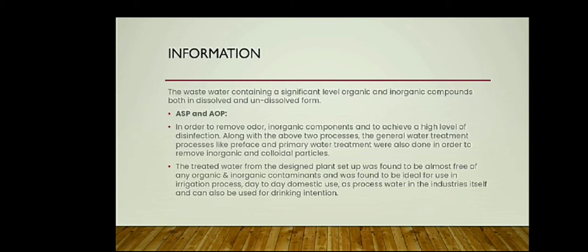This water treatment process basically utilizes the ASP, that is activated sludge process, and AOP, that is advanced oxidation process, which are not only highly efficient in organic and inorganic compounds removal but also provide a high level of disinfection. In ASP, microorganisms are cultured in the ASP tank and removal of organic compounds takes place. In the AOP tank, UV light is used with H2O2 in order to remove other inorganic components and to achieve a high level of disinfection.